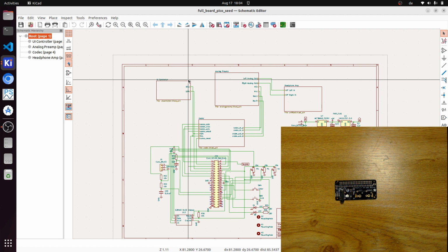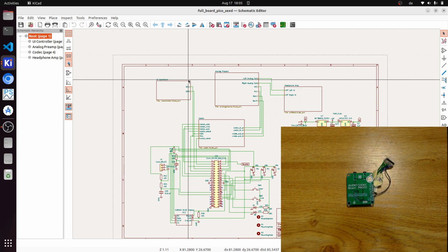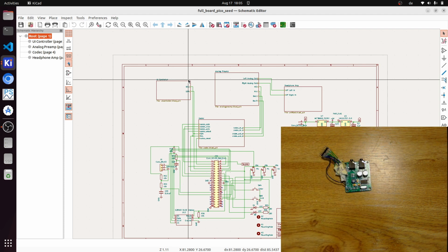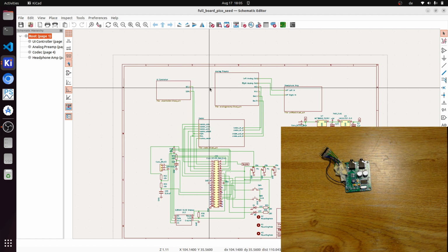But this is only the digital to analog converter part, and I found that it's difficult to find boards which have both ADC and DAC. One I actually found was this audio codec board Proto from Microelectronica, I think it's called. And this I used, but this used a little bit outdated codec, which was difficult to handle, and also I wanted to have a guitar input and not a microphone output, and also I wanted to wire it up directly and not to use these 3.5mm jack connectors.